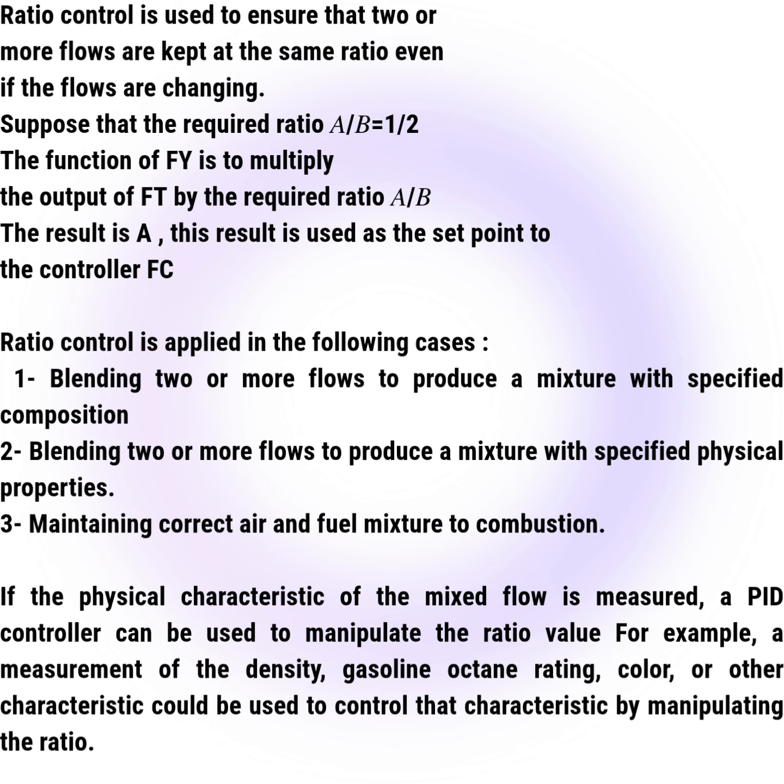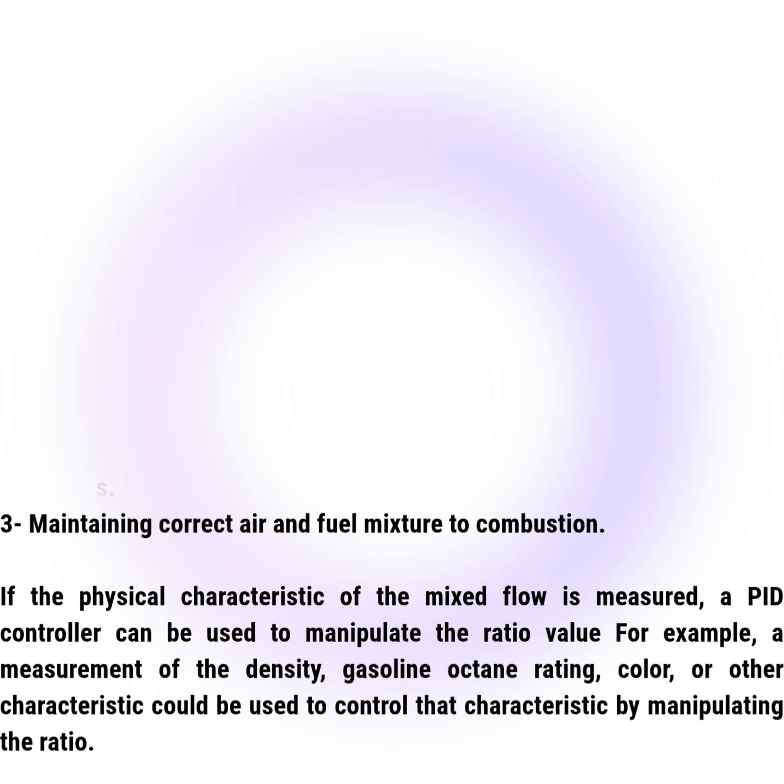If the physical characteristic of the mixed flow is measured, a PID controller can be used to manipulate the ratio value. For example, a measurement of the density, gasoline octane rating, color, or other characteristic could be used to control that characteristic by manipulating the ratio.